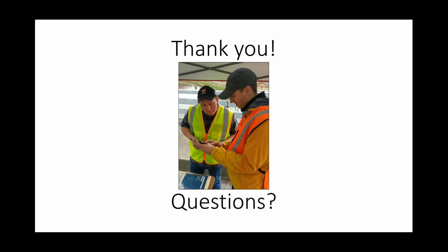Sure. So with some of our field work, and as we get more comfortable with these systems, we're trying to develop just a one-pager, basically instructions that somebody could use to take a mobile device out to a bridge, set it down, watch a changing frequency response spectrum in order to pick up some dominant frequencies.